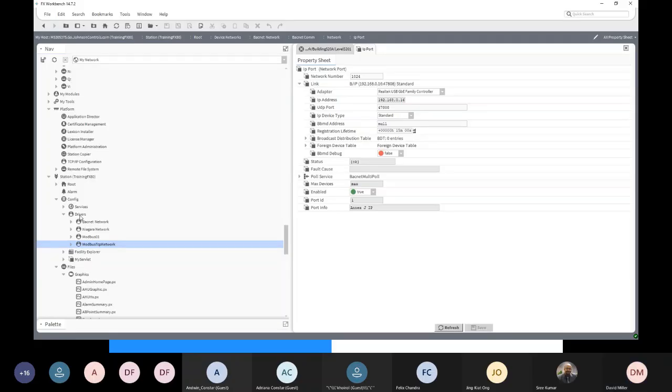And so you could have 1 BACnet MSTP, 1 Modbus, or 2 Modbus, 3 Modbus, 4 Modbus. So the number of physical ports is a limit, and the other limit is your device license. So you can have all of the available protocols into an FX80, provided you've got enough device licenses to cover all of the devices that you've mapped.